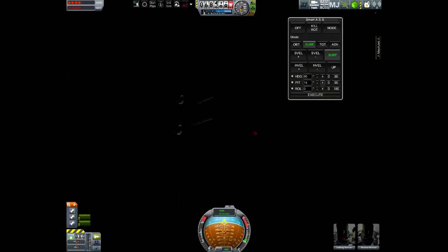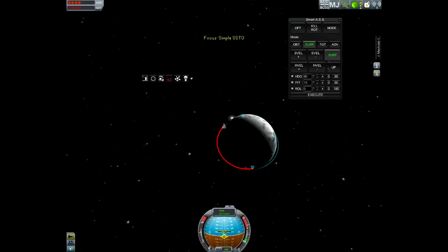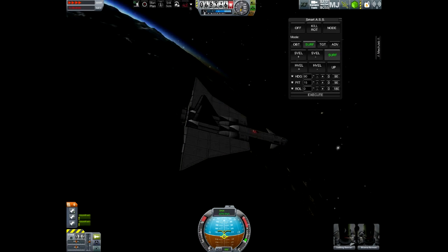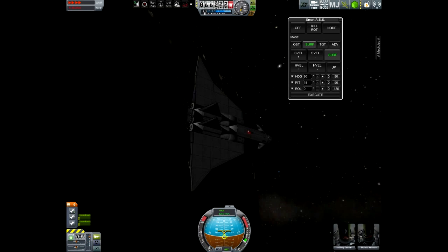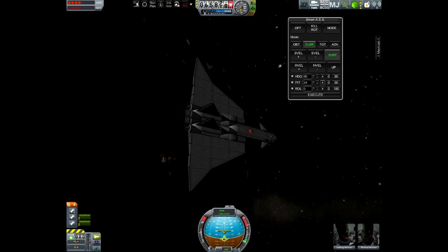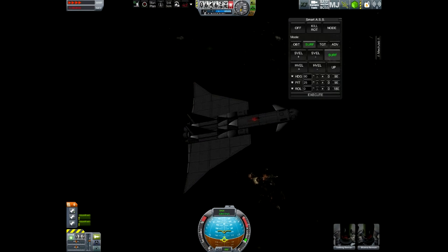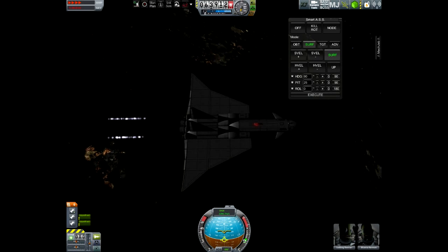Now, as an optimum angle to enter the atmosphere, or re-enter the atmosphere, there is a lot of variation, depending on how big your wingspan is. Like for example, for a space shuttle you need like a 45-degree angle. For this airplane, because it has a bigger wing area, I'm going to start the descent with 25-degree. If we need more or less, we will adjust it on the way down.